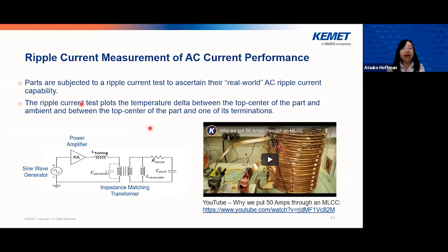When you get into high frequency switching components, you will see waveform that are not completely sinusoidal. So, we always tell customers we can provide our typical ripple current plots for MLCCs. And we always recommend customers to put our parts on their board and then test to verify.